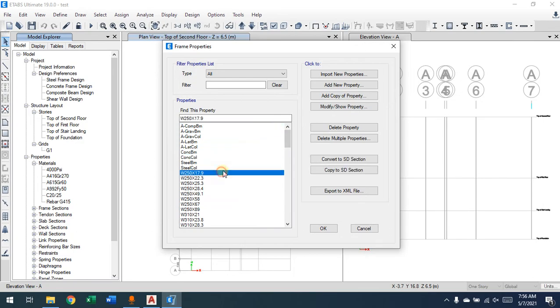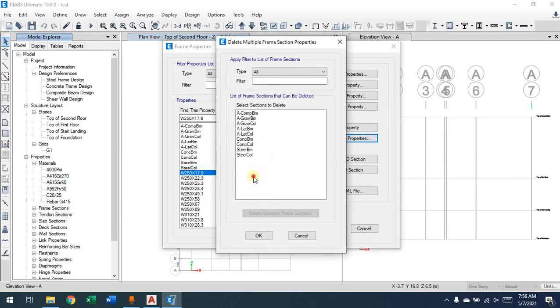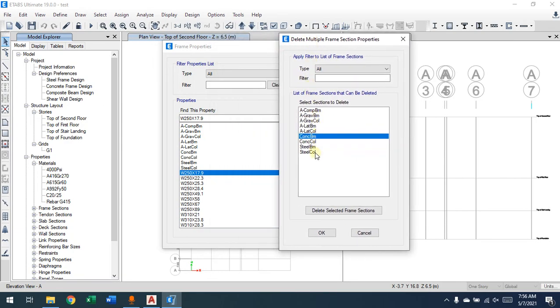Let's go for new. I'll leave this one here. I can delete those, the things inside here: columns, beams. Why are they added this way? Because Revit will use this one for design. Under concrete column, there are a lot of sections, and the concrete beam, steel beam, there are a lot of sections. Now, if I want to delete them, yes, I'll delete those.